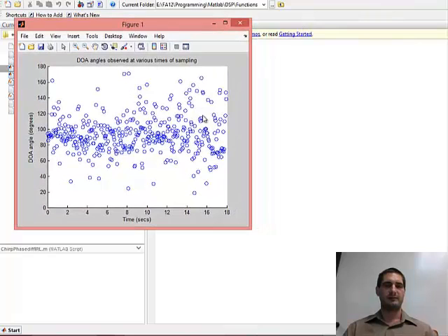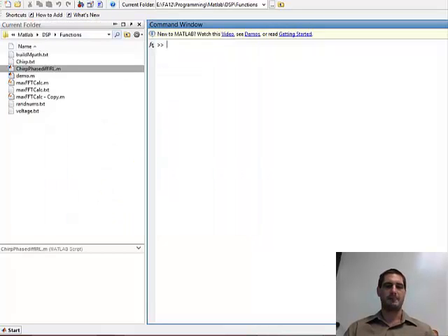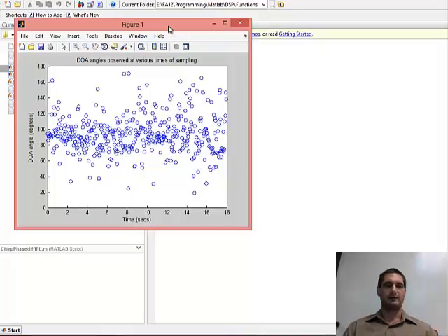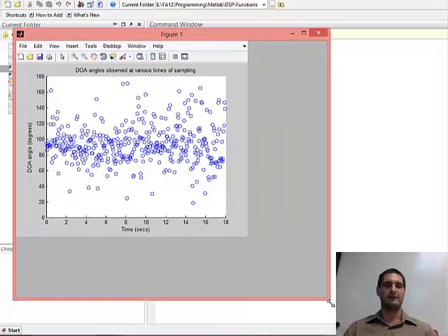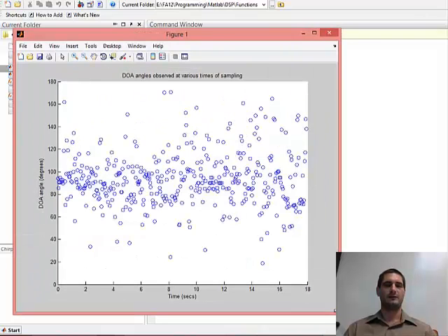Now, when we performed these measurements, they were performed in an enclosed room, and we moved about 180 degrees relative to the right antenna in a clockwise fashion, with a radius of 15 feet away from the antennas, and we stopped when we were at 0 degrees relative to the right antenna. As you can see here, the direction of arrival measurements are less than optimal. This is most likely due to performing in an enclosed room where multipath can become a problem.